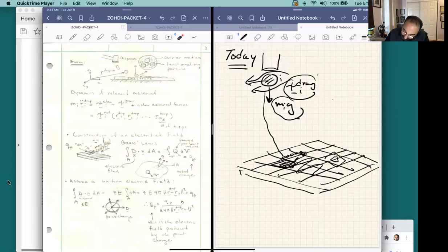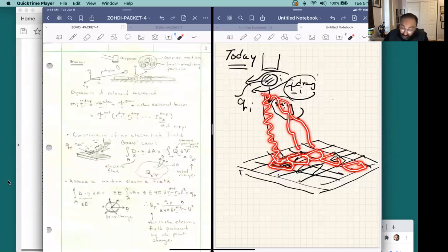We'll electrify this one momentarily with some kind of a charge. And we'll basically have an electrical force that is going to guide this thing to that location, just to that pixel, one at a time. And we're going to do this over and over again at each of these pixels. We're going to turn them off and on each time, attracting the particles to those locations. That's, of course, the basis of electrohydrodynamic printing.